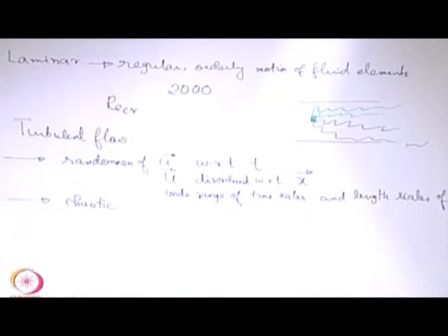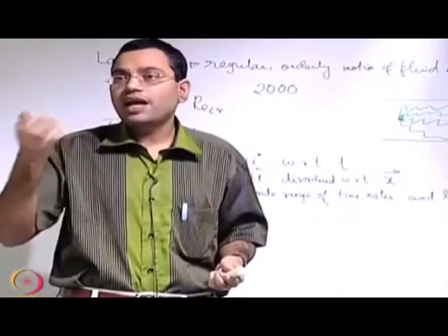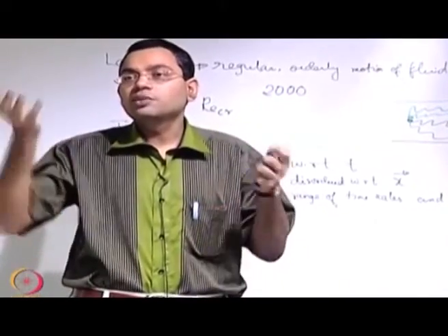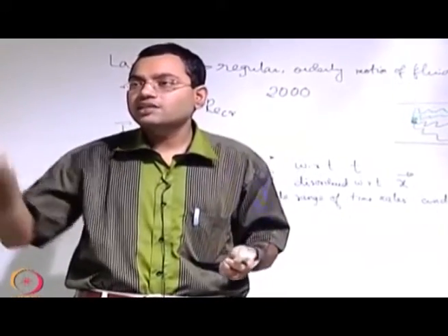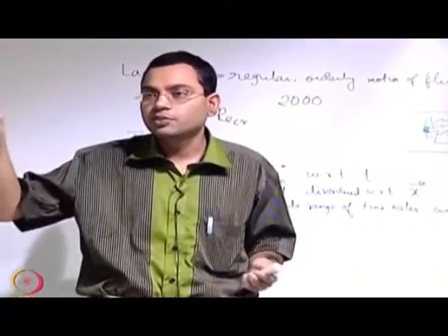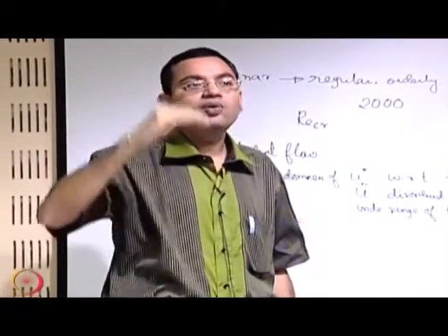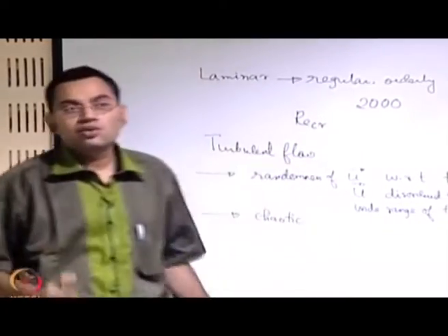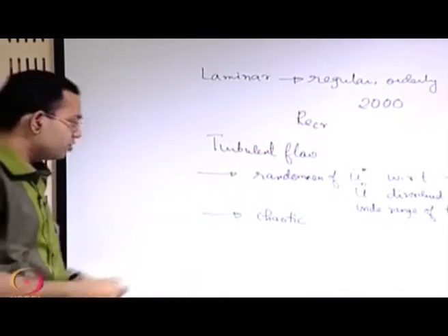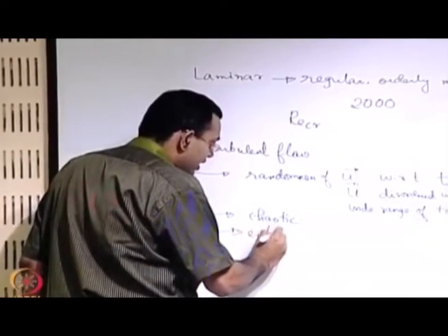So, turbulent flow will first be triggered like this: you have a base type of flow and you have a disturbance on that, the disturbance gets amplified, so it goes to an unstable state, and that unstable state again interacts with the mean flow and takes it to a further different unstable state, because these are non-linear interactions. At the end it will go to a completely chaotic state throughout the domain, and that is the so-called turbulent state. The turbulent state will have enhanced mixing and diffusion.